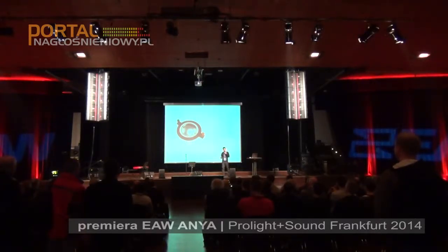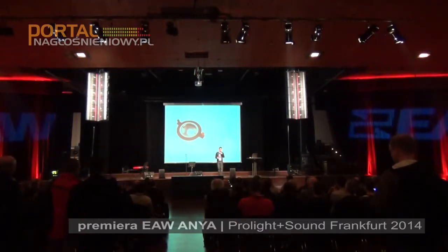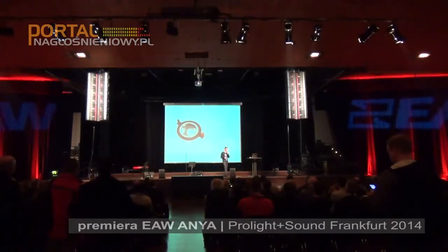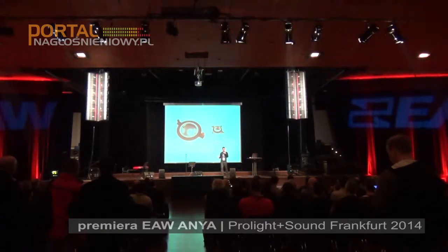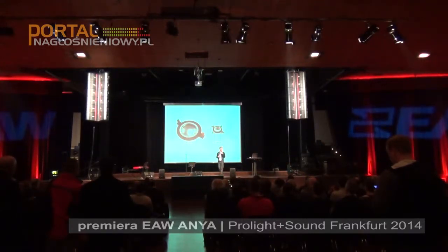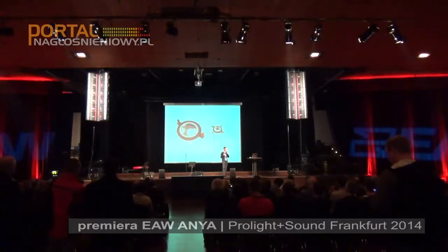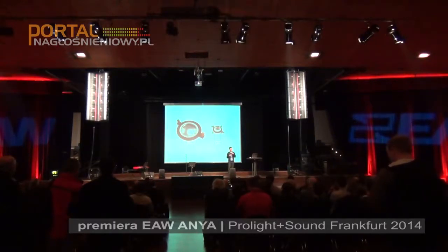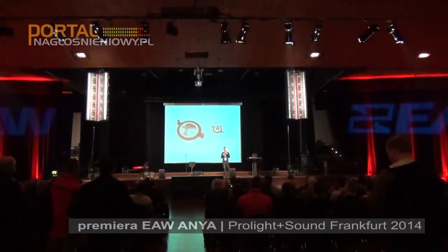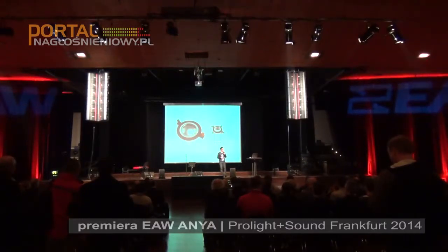So, very similar to the 15-inch woofer, we started really from the ground up on a new design that resulted in a 35 millimeter voice coil device with every aspect of the design optimized and refined to precisely match our needs. Most notably, a specifically designed neodymium magnet structure that's asymmetric, giving us the ability to get the extremely tight vertical spacing that we require.